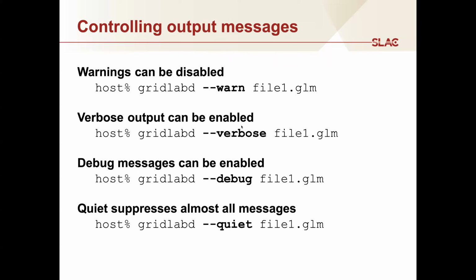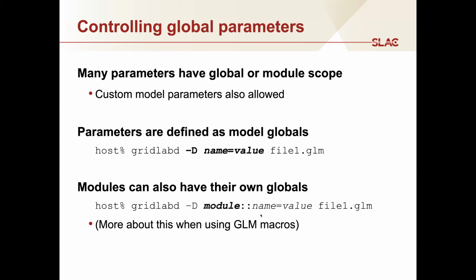Verbose obviously affects whether the verbose mode is turned on. Same thing with debug. And then quiet essentially suppresses just about all the messages that would come out of the simulator, I believe, with the exception of exceptions. I don't think quiet suppresses exceptions. Okay.